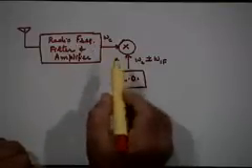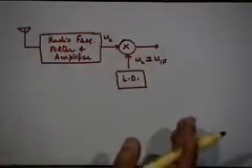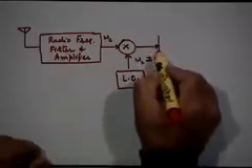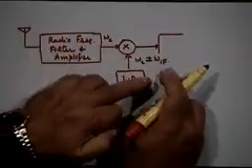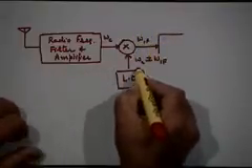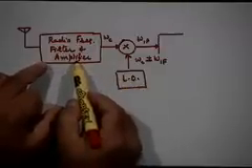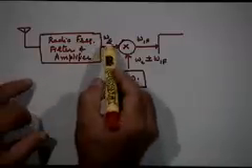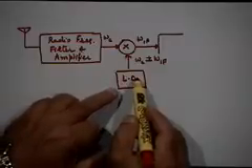If it is omega IF, so that the converted frequency is omega IF, right. And now no matter what the input signal is here, this will always be omega IF. The output here will always be at omega IF. Of course, you will have to make sure that these two things, the filter and amplifier combination here and the local oscillator here, are tuned together, so that if you tune this to a different frequency, this also generates a different frequency, right.